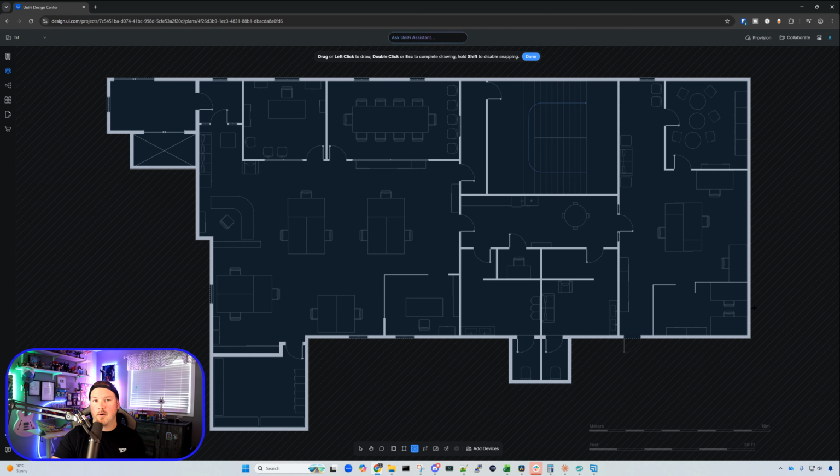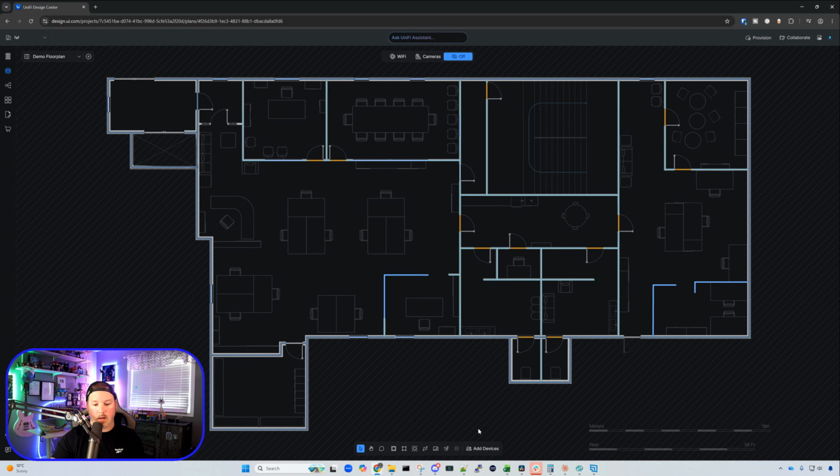Now, if there's an area that you don't want to be part of this zone, you could click back on Wi-Fi zones. And right here with the X through it, I'm going to pretend that that's an elevator shaft, and I'm going to create a new zone. Once we create the rectangle and exit, you can see that there's lines through it. So we won't see Wi-Fi within that spot. And I'll show you what I'm talking about.